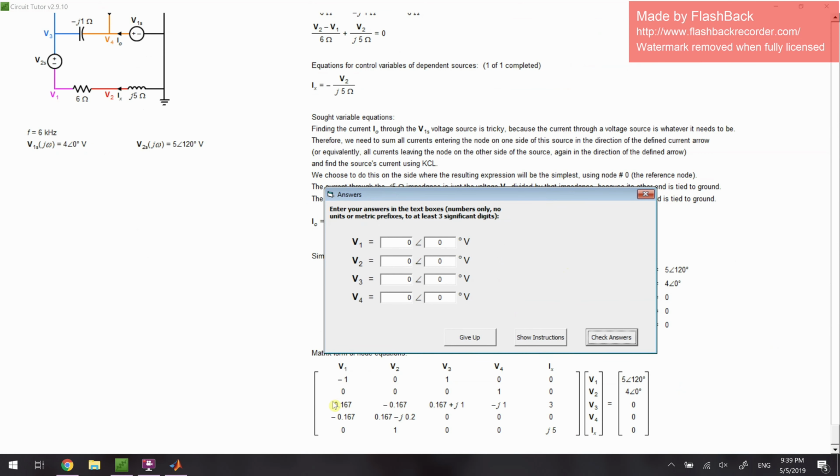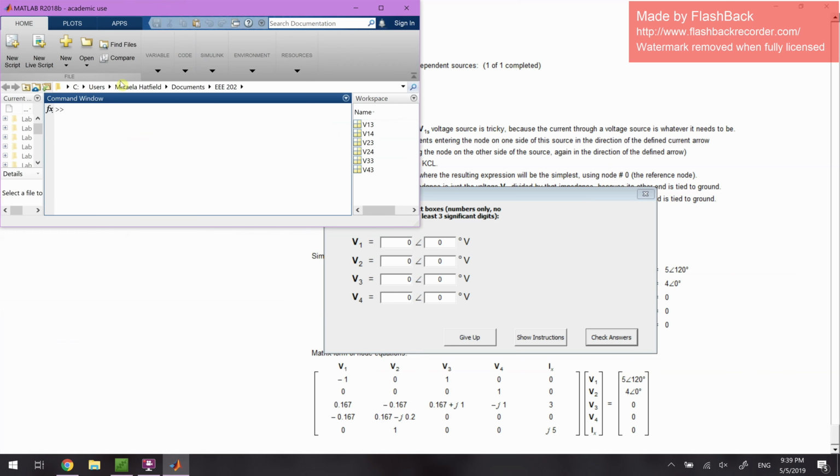And for that, I'm going to use MATLAB. So if you recall how to enter syntactically an equation, a matrix of equations, then this will go real fast. You can also see how I'm doing it on the screen right now. I've accelerated the speed because it's a little boring, but the gist of it is that you go from left to right, top to bottom, put a space in between each element, and then a semicolon when you're starting a new row. So you can see my mouse tracing the movement that you should be taking right now when you're entering the values.